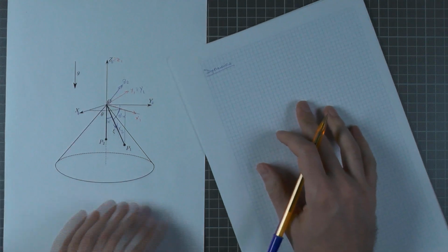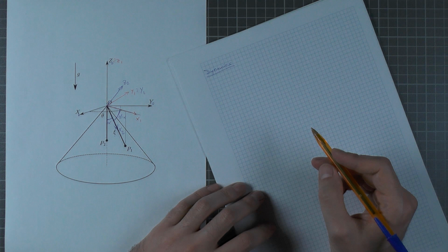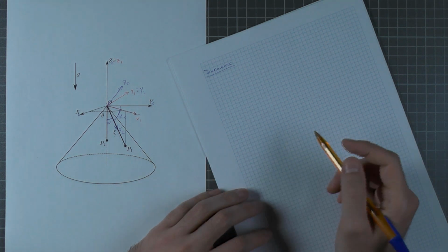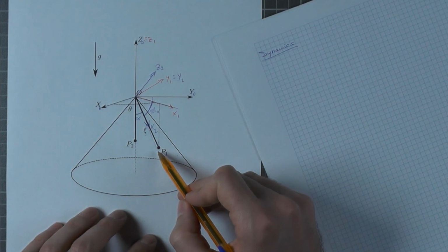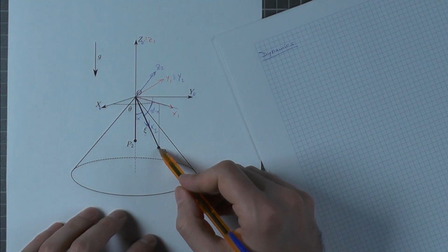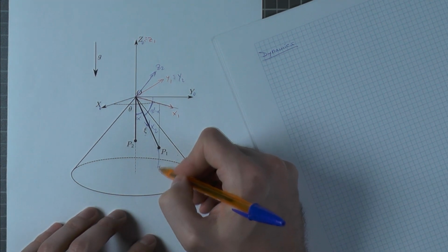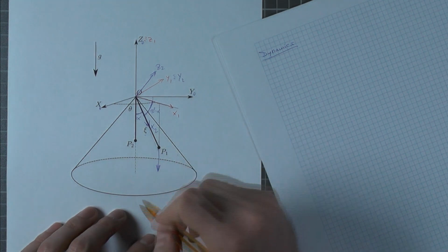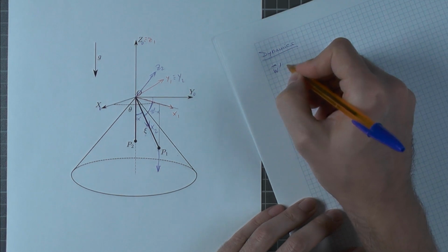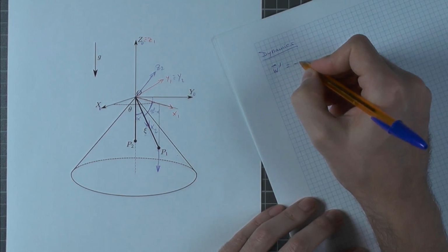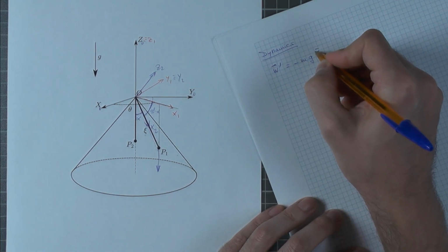Okay, so the first thing in the study of the dynamics of the particles is to identify and write down all the forces that are acting on them. So if we consider P1, for example, we can see that since this is a heavy particle with mass m and there is a gravity vector over here, there is a weight force pointing downwards, okay, which we are going to write as W1, okay, and its mathematical expression is minus mg in the K1 direction. All right.